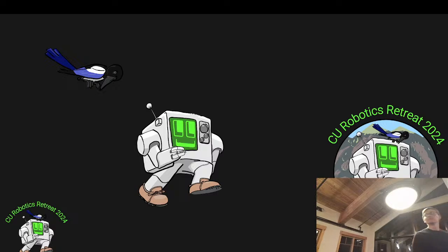Ryan, do you mind if I add one thing too? Sure. So Ryan taught me about the oversampling problem that he was demoing in this workshop, and I had just finished reviewing a paper, and I was looking at the data in one of their plots, and I was like, this sensor data is so noisy, and it was an ultrasonic sensor, using this exact sensor. And then when Ryan started showing me his workshop, I realized what they were doing is oversampling the sensor, and they were using it as a ground truth sensor for depth mapping.